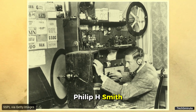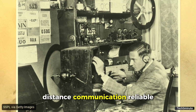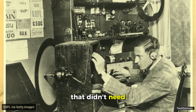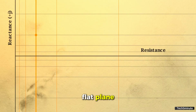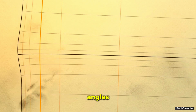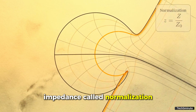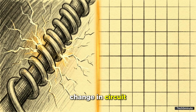Philip H. Smith, a young engineer at Bell Labs, realized making long-distance communication reliable required a mathematical transformation that didn't need infinite paper. He turned to conformal mapping, a mathematical technique that bends a flat plane while preserving intersecting angles. By dividing circuit impedances by baseline impedance, called normalization, Smith pulled those infinite points toward a central origin. This wasn't a change in circuit physics, but a change in the coordinate system.